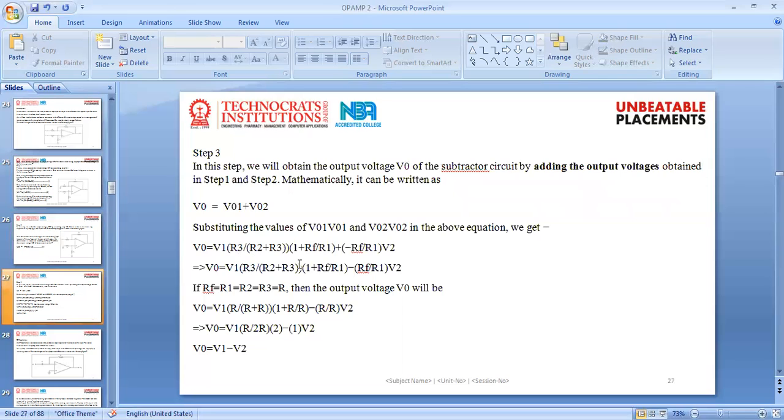So here we will put the values of V01 and V02. As soon as we put the values of V01 and V02, and RF equal to R1 equal to R2 equal to R3 equal to R, the V0 that comes is V0 equal to V1 minus V2. Note that this one is the difference between the input voltages. Output voltage equal to the difference between the input voltages, V1 minus V2.